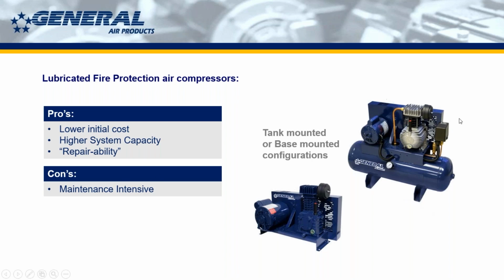Repairability is something that we refer to, in that if the electrician fries the motor by bringing the wrong power, or somebody, which is another very common thing, doesn't add oil to the pump, you can replace just the pump or just the motor. But on the other hand, these are maintenance intensive as compared to the oilless units. You need to make sure that you maintain that pump with oil. You need to take a look at the flywheel and the belt on a regular basis.